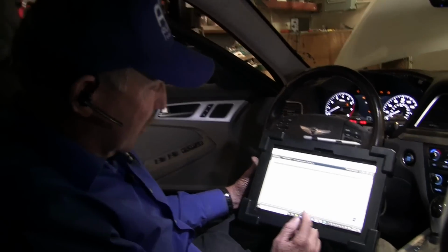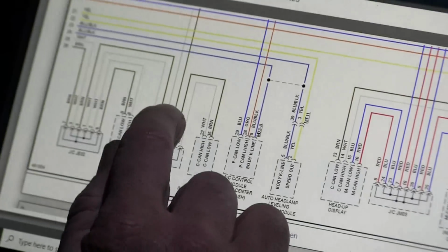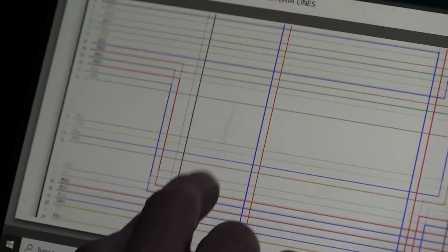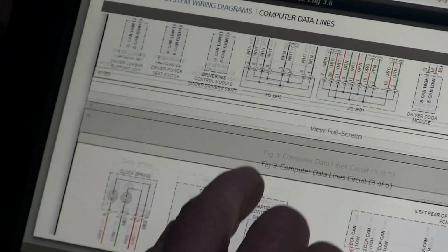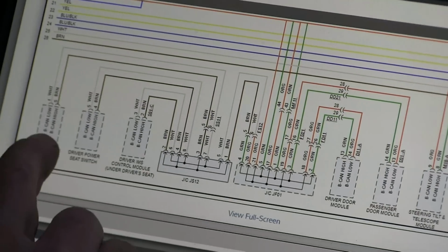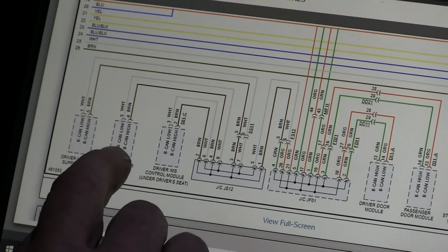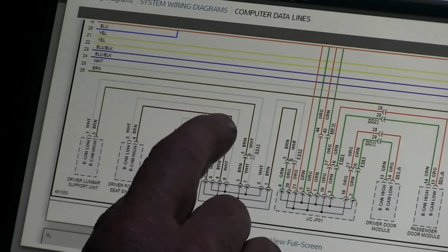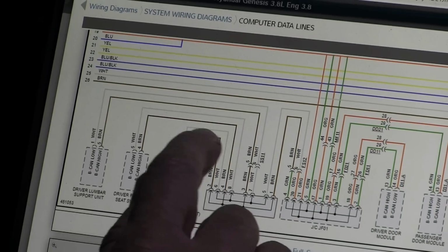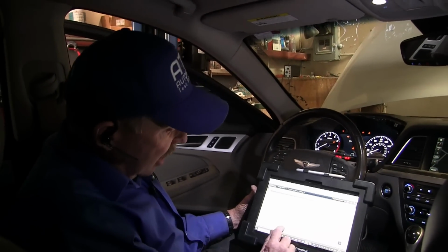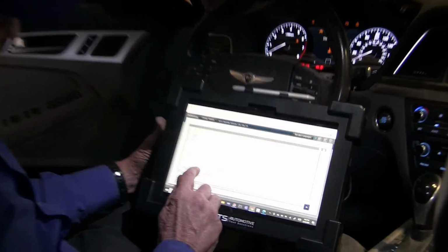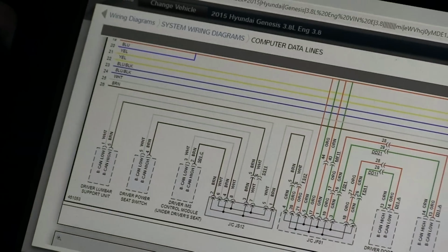But I do want to make one more note here that's really interesting. I saw something when I was just going through here, where we have brown wires right here. Look at these. Do you see how this is marked BCAN, and they're brown and white? Okay, now the brown and white wires are going to a bus structure, and you could get really confused on this. Don't get confused. Always look at the designations of what they are. A BCAN is a medium speed bus.